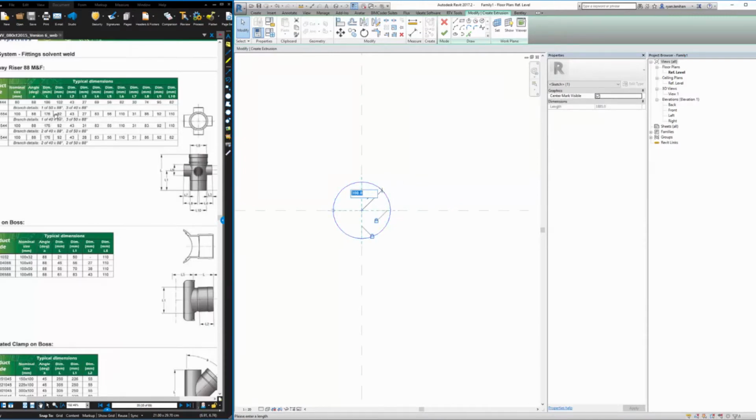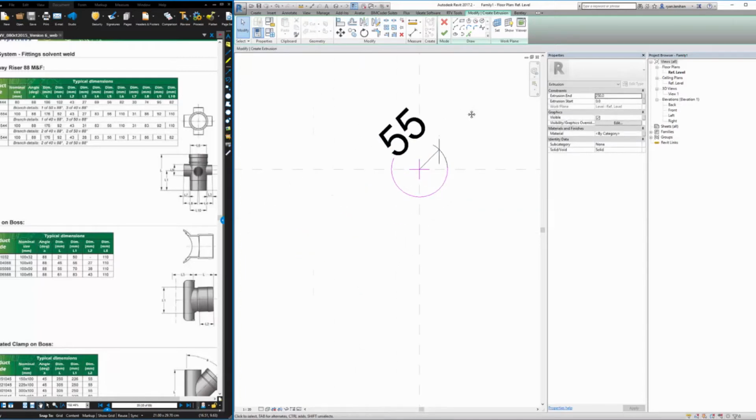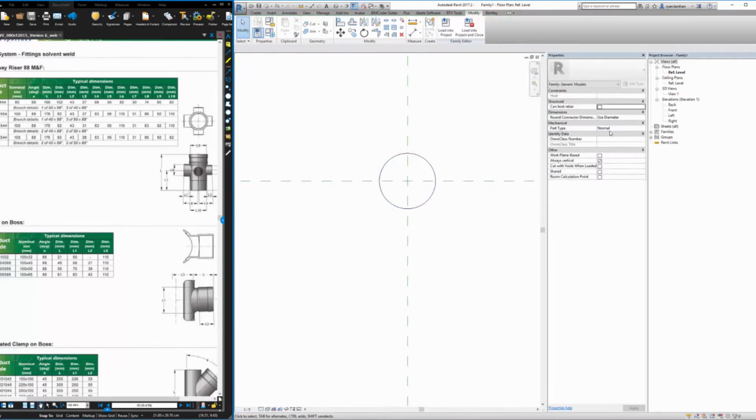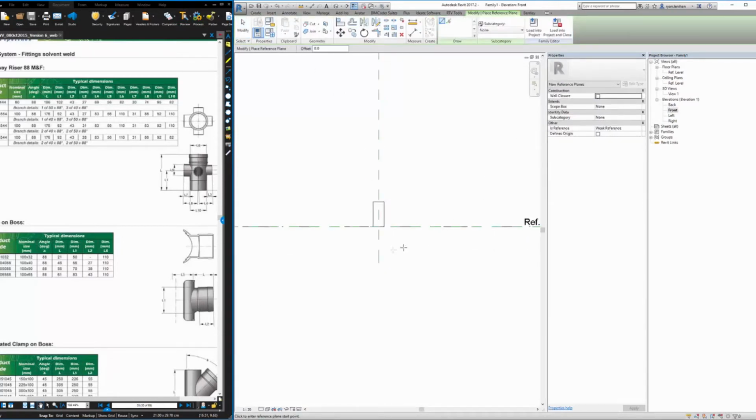I'm set here tonight to talk over the top of a video that I recorded a long, long time ago on how to create a four-way riser and floorway gully for hydraulics in Australia. I mean, Iplex, we're basing this off an Iplex product and it's an Australian brand. So we're starting off here with the riser of the four-way riser. And it's 110 mil external diameter.